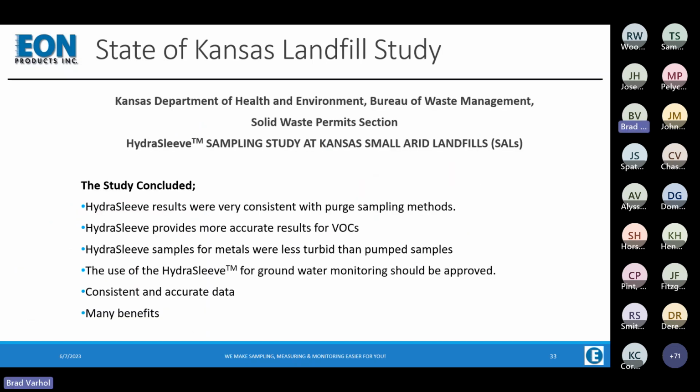The State of Kansas did a landfill study and concluded that hydrosleeve results were very consistent with their purge methods. Hydrosleeve provides more accurate results for VOCs, and that was because they weren't aerating the sample. Hydrosleeves for metals were less turbid than the pump samples, and they concluded that the use of hydrosleeves should be approved because it provides consistent and accurate data with many benefits. And the State of Kansas directly purchases, and has their contractors purchase, hydrosleeves for their landfill sites.